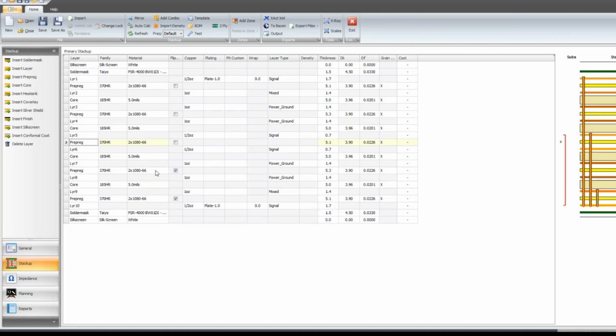But you can achieve the same thickness in multiple different ways with most manufacturers' pre-preg sets. You can buy thicker pre-pregs and thinner pre-pregs and combine them in different ways to achieve the same end thickness. And so the planning process evaluates those characteristics and puts them together, depending on the right mix of maybe there's impedance requirements or very specific thickness requirements, or it's just about cost and ease of production.